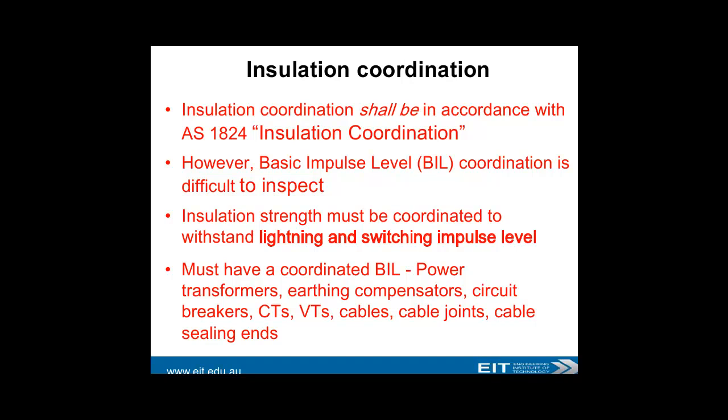Big issue with high voltage, of course, is insulation. So there's a lot of discussion there about insulation coordination. Basic impulse level coordination is difficult to inspect. You obviously can't look at insulation very easily and say, look, that's fine. You obviously need some form of testing. And it must be able to withstand lightning and switching impulse levels.